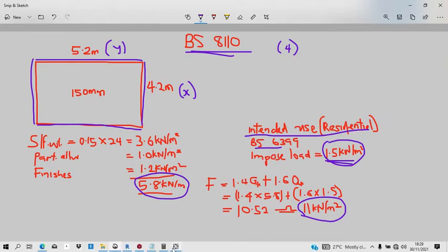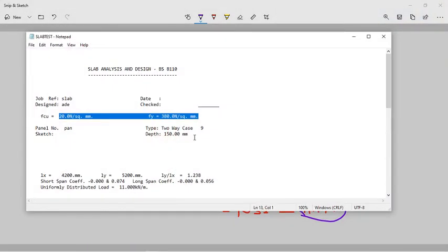So, and also again, the diameter of the reinforcement that's in the market is not complete. What I mean by that is that where you're supposed to have 12 dia, by the time you use your caliper to check it, you discover that they are lower than 12 mm. 16, you might be getting 14 for 16 dia bar. So it's just unfortunate we find ourselves in such situation.